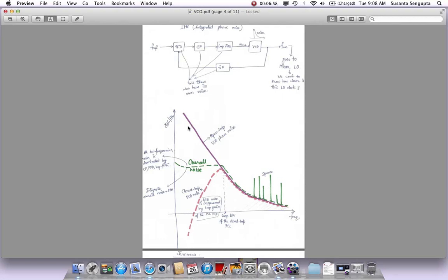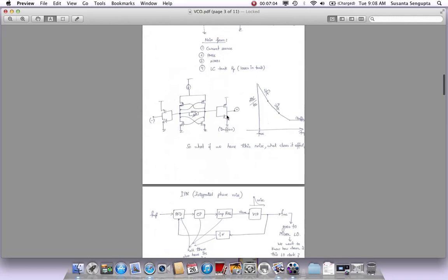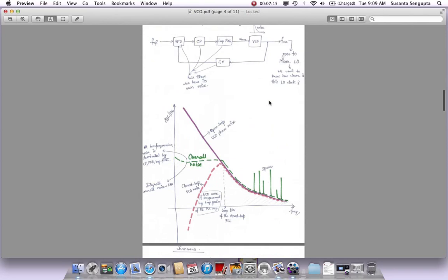Okay, so it's suppressed significantly. All the low frequency noise, remember it looked really bad, that VCO low frequency noise. Ooh, that is very, very high because of the 1 over f cube region, right? But that is not what we really worry about so much, because all that is actually handled by the PLL and it actually suppresses it. So this point, when divided by the loop gain that we have at lower frequencies, it actually gets knocked down way lower.